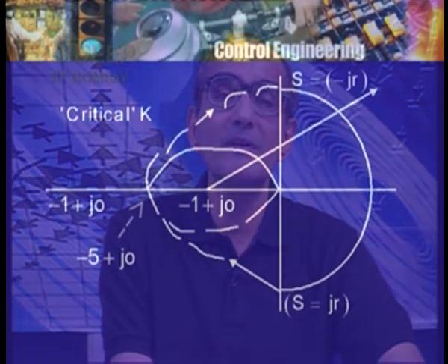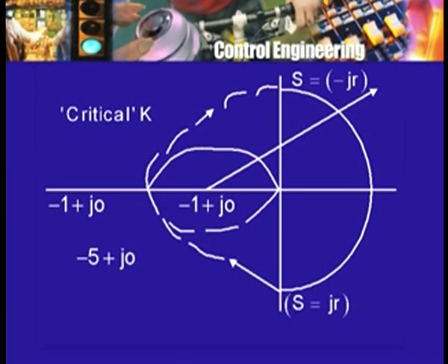Phase shift 180 is important because it gives you this point. The real axis or the real part or the real number that corresponds to this point is important because it determines very often the encirclement of the point -1 plus j0.